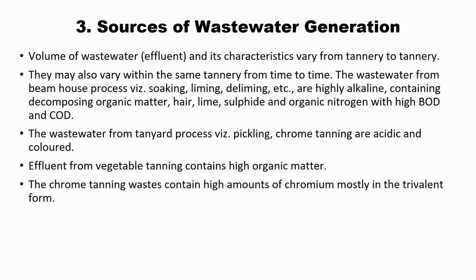Also, we have to see the concentration of BOD, COD, organic nitrogen, and sulfide. Wastewater from the beam houses, which is soaking, liming, and deliming, is highly alkaline, containing decomposing organic matter, hair, lime, sulfide, and organic matter with high BOD and COD. So all the processes don't have the same concentration of BOD or COD.